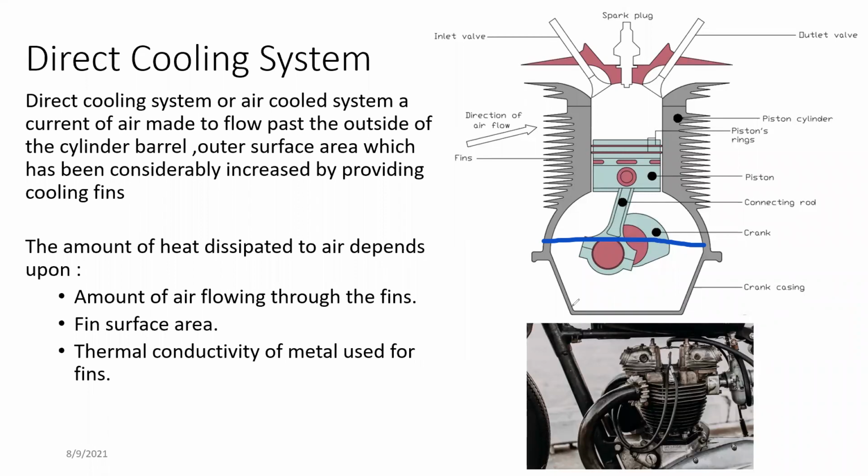So in most of these engines, if it is a large engine, not like a motorbike, these actually need additional cooling as well. But in motorcycles also, if you look at the underneath of the motorbikes, they have fins underneath the engine bay itself just to cool the oil inside the gearbox and the transfer case.